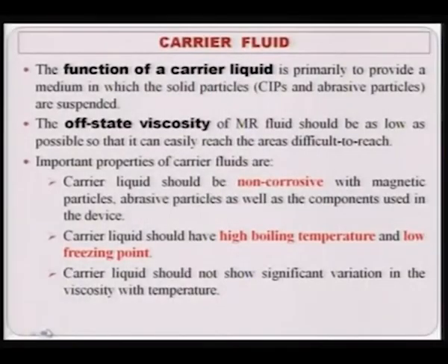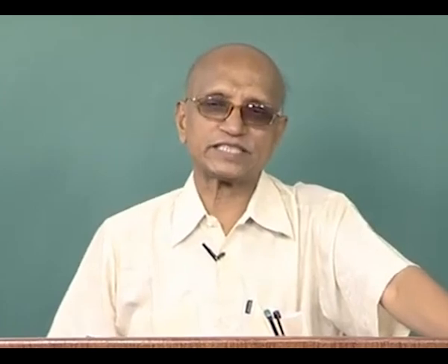Carrier liquid should not show significant variation in viscosity with temperature. As I just mentioned, the temperature is changing, and with the change in temperature, the viscosity of the carrier fluid should not change substantially, otherwise it will not remain in the designed parameter condition, and then definitely you are not going to get the desired finishing rate and final surface roughness value.